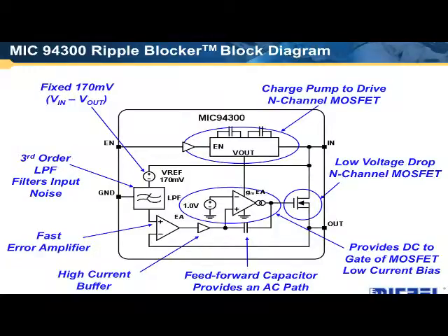The value of that reference is chosen to meet two things. We use an NMOS output stage, a power FET, as a follower. So we have to keep that device just into the active region, which is the optimum position for best power supply rejection for a given voltage drop.